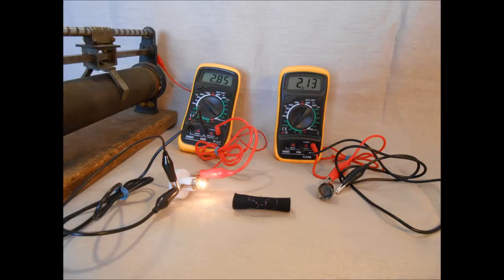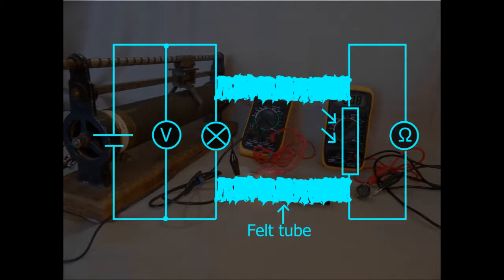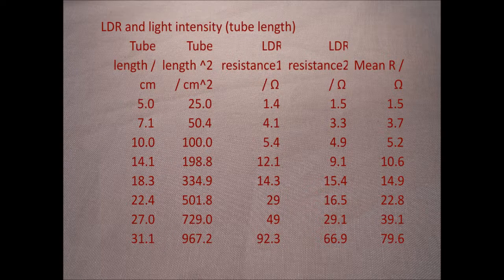Okay, this is the kit that I used to test this relationship. We've got a light source, we've got the little felt tube, and I've stuck a bit of gaffer tape around the light dependent resistor so that it seals well into the bottom of the tube. This is the kit assembled for a measurement. What we're measuring here is the voltage across the power supply, just to make sure it doesn't vary during the experiments. Because of the range of meters I've got, the light dependent resistor is stuck straight into an ohm meter.